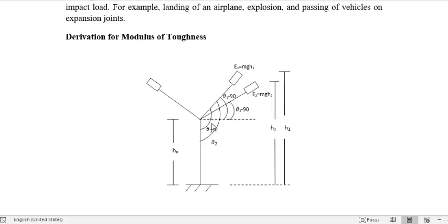And in the second run, for the bend test, we will place the specimen in the path of the hammer somewhere over here, and when the hammer rotates, it will strike the specimen and the specimen will be broken, and some of the energy of the hammer will be absorbed in the specimen during the process of breaking. As a result, for the second run, the hammer will achieve less height, and the energy in this case will be denoted by E2, and it can be calculated as mgh2, where m is the mass that remains the same, g is the same, and h2 is the maximum height achieved by the hammer, and it is denoted here on the diagram. Now these heights h1 and h2 will be calculated using these theta measurements.